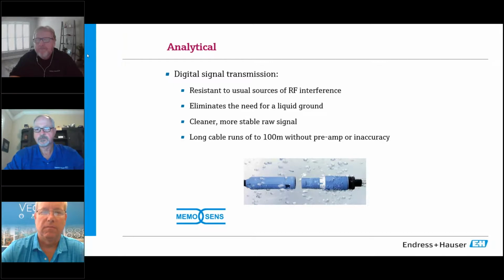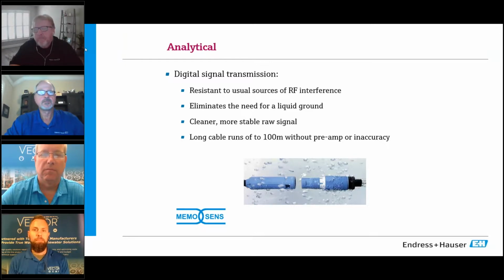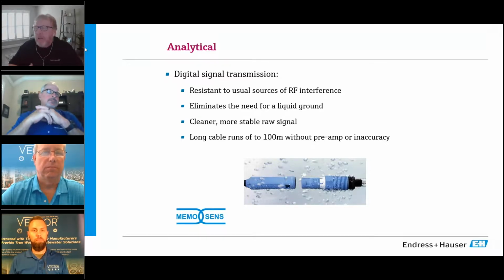Can a sensor with the inductive head be completely submerged? Yeah, I can take that one. We do show the picture that you see with water, so I don't want to mislead you at all. The sensor is not rated for IP68, so we do not recommend that the sensor be fully submerged. If you fully submerge a sensor, what happens typically is at the back where the cable comes into that holder, eventually you will have water ingress come in there, and obviously you're going to probably short the sensor.